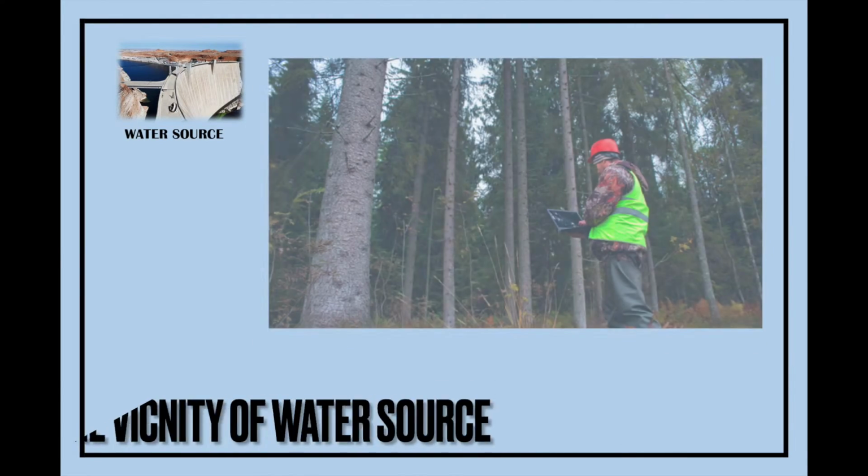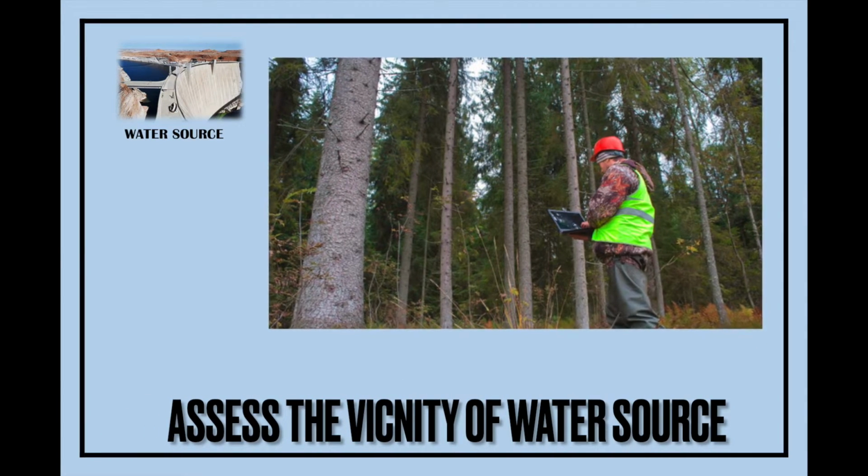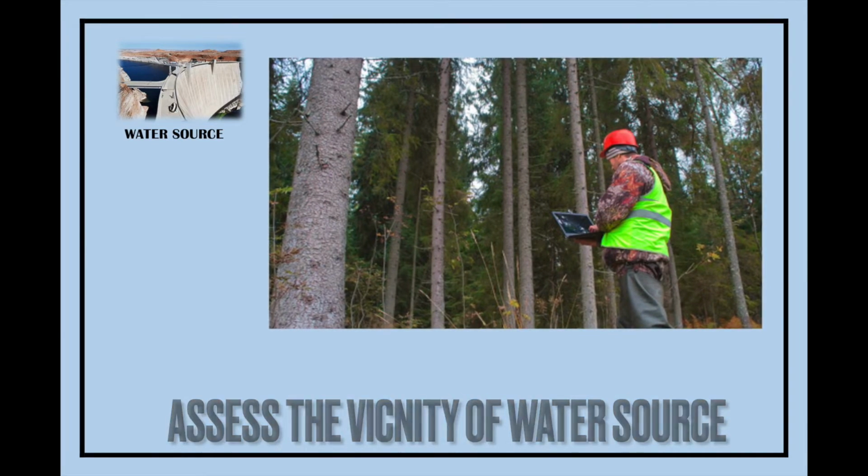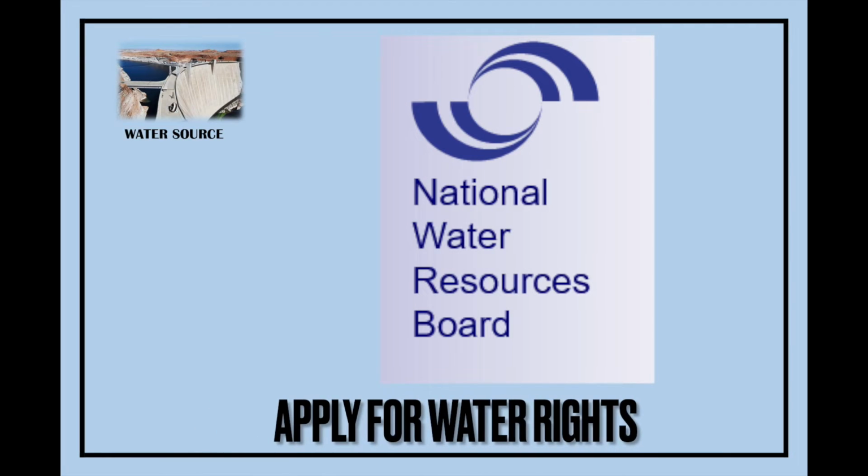Third, assess the vicinity of the water source. Determine its ownership or check the legality should the source be developed. Also, apply for necessary permits such as water rights at the National Water Resource Board, NWRB.